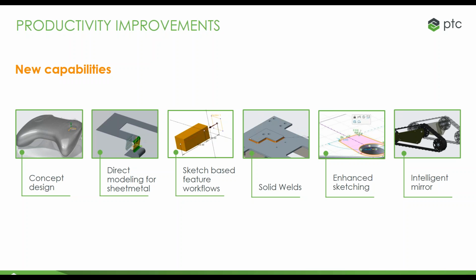Moving side 2 in a negative direction will now remove material, simplifying your model construction and eliminating the need to construct additional geometry. And finally, adding the ability to extrude to the offset of a reference. Again, this will consolidate multiple tasks and simplify the overall process.